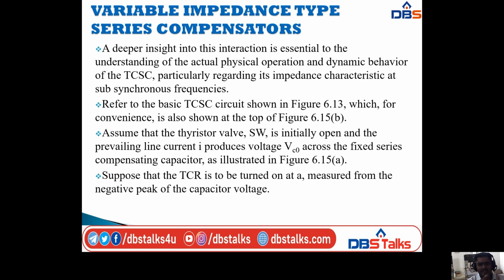A deeper insight into this interaction, that is the interaction of the TCR in connection with the capacitor, is essential to the understanding of the actual physical operation and dynamic behavior of the TCSC, particularly regarding its impedance characteristic at subsynchronous frequencies.